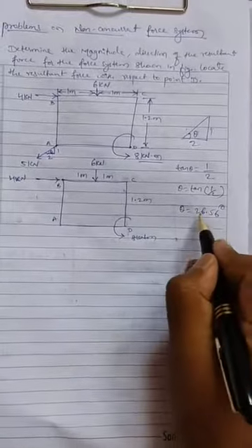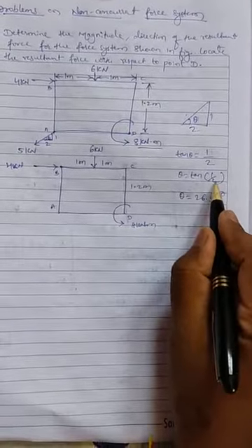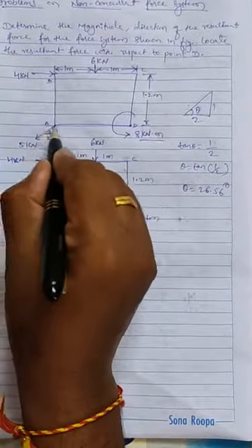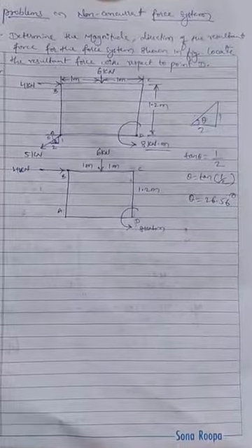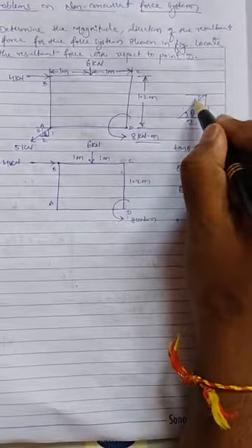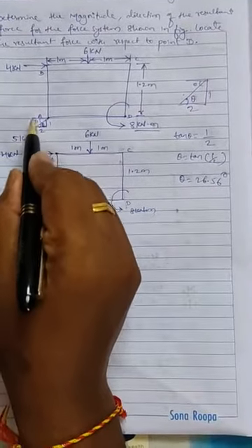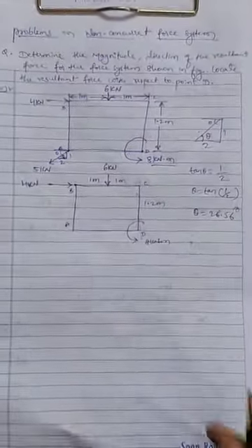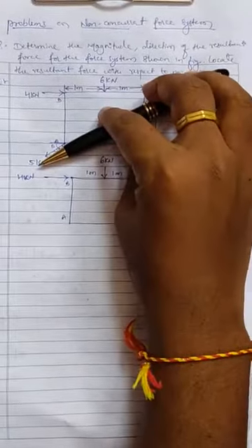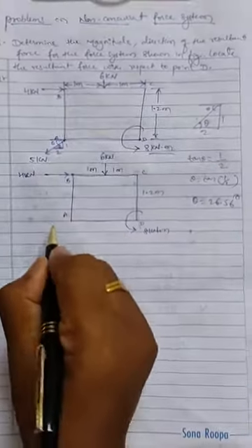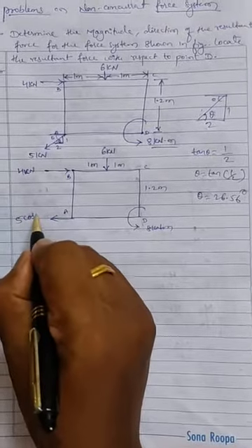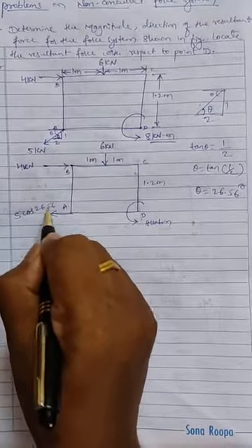It's the angle. Whatever angle we have calculated is with respect to the base, which means with respect to the x-axis. So whatever angle is given for this force is with respect to the x-axis. It is something like this, so this angle and this angle will be the same. So I have taken the angle for this 5 kilonewton with respect to x. When I resolve this 5 kilonewton, I need to bring it along x. It is acting towards left. Show the direction toward left, and it is 5 cos of the angle theta, where theta is 26.56.